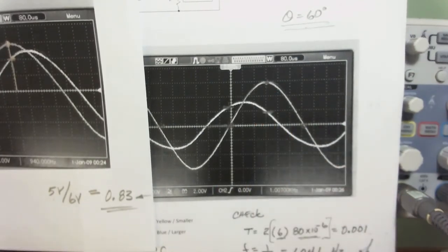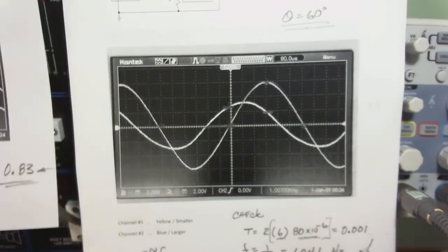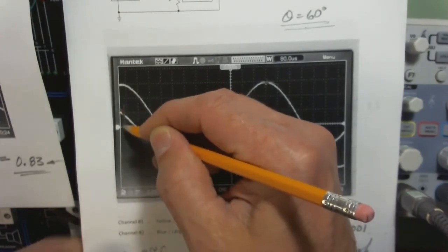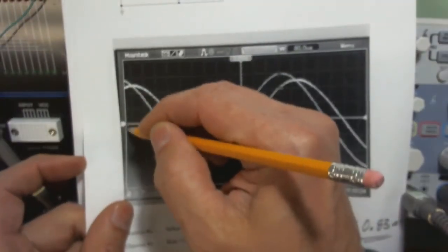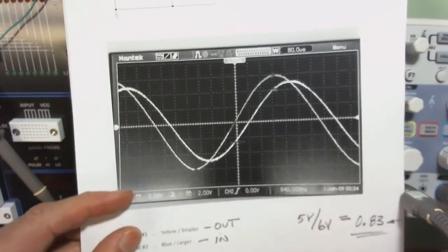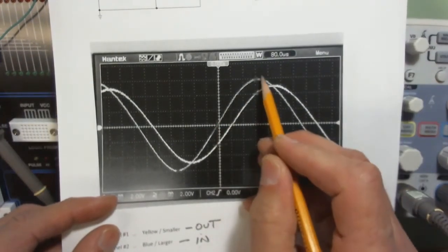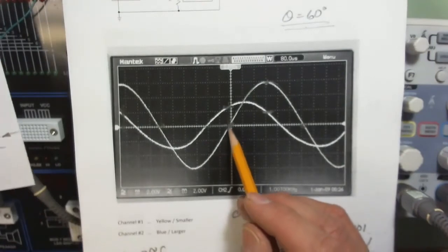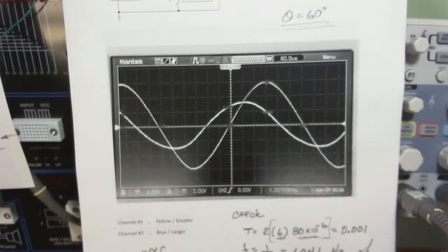So indeed, the answer is yeah, Kirchhoff's law works. There was no stipulation that Kirchhoff's law only worked for DC. It works for AC, it works for DC. And you can actually show that. But the big thing is you have to show it for a consistent time. And time, for instance, when you look at these waves here, if you just say that over here on the left-hand side, that is not probably the same time as over here. So what I do is I find the same time by referencing it to a known point on one of the waves. I take this one as the input, and I say I'm going to always look at the same time on that one. And Kirchhoff's law will work.